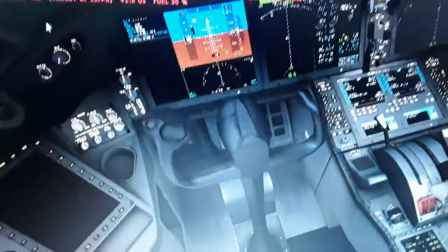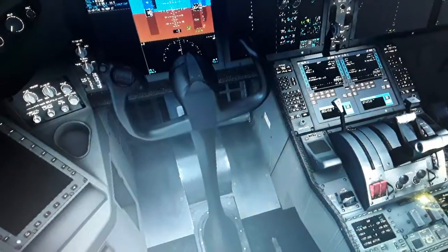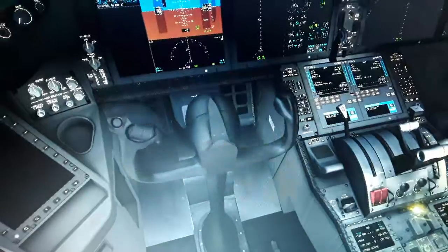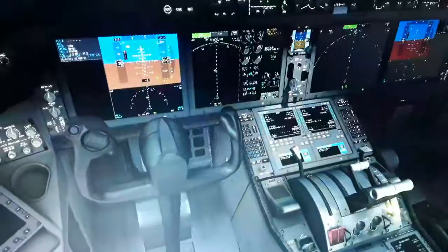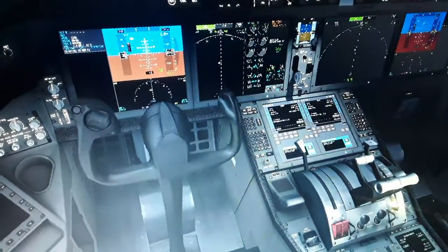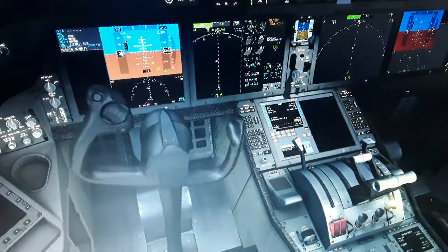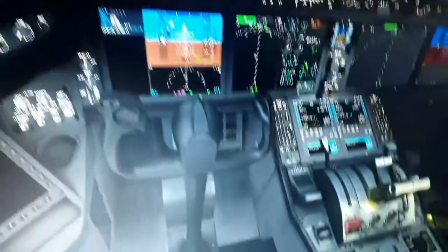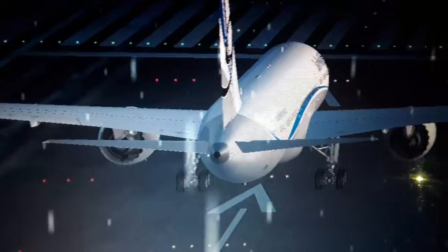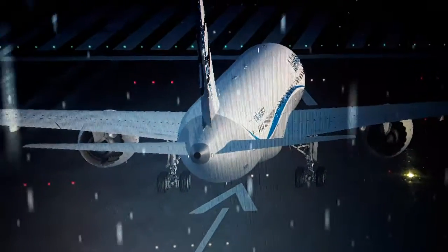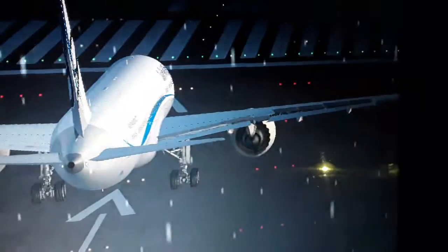So you can see here we have the cockpit. You can see the flight control, the control yoke and the control column. We control the elevator of the aircraft and the ailerons and the spoilers with that by pulling it up and down. We control the elevator, while turning the wheel left and right makes the ailerons and the spoilers in its wing turn left and right, as you can see here also. So this is the elevator and the rudder and some of the ailerons and spoilers, as you can see.